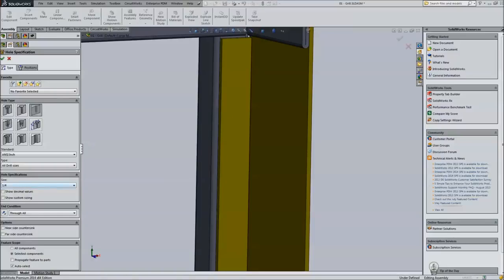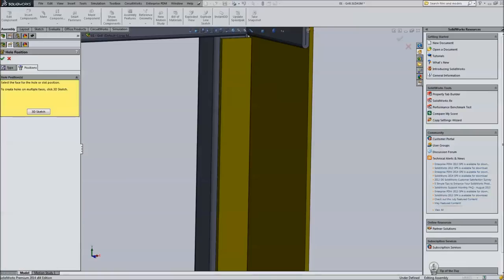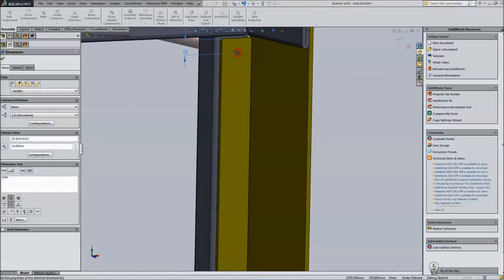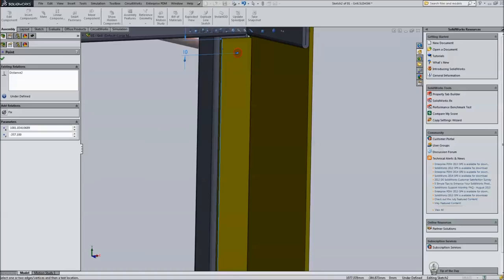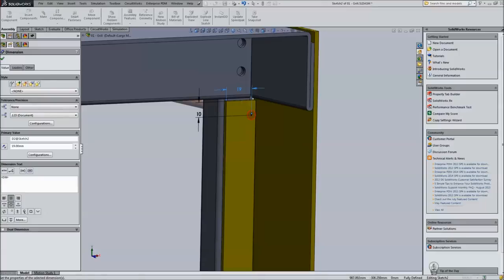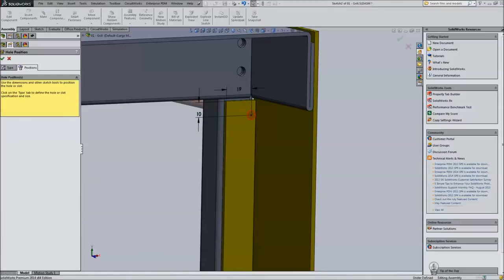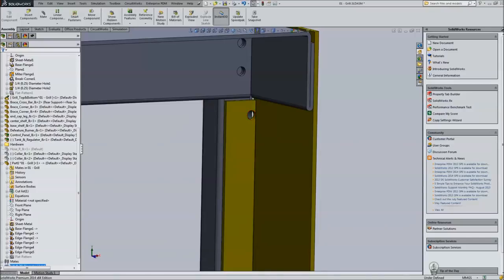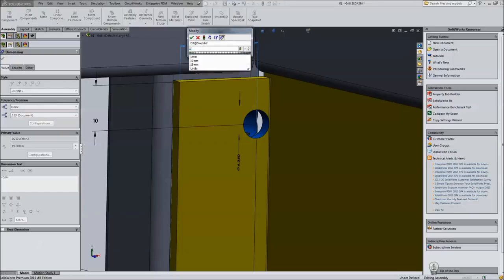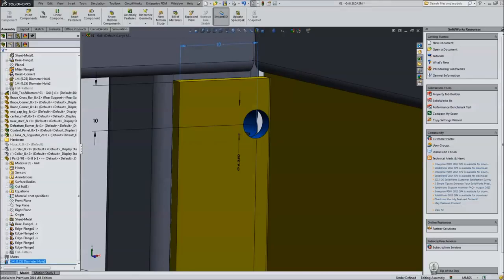And in this case, I have a hole. It's a 1/4 inch hole through all. So same things we had earlier. Same settings. Nothing's changed. I'm just using the hole wizard up at the assembly level versus at the part level. Move that out of the way first. All right. I'm going to hit OK. Make that 10. Rebuild.